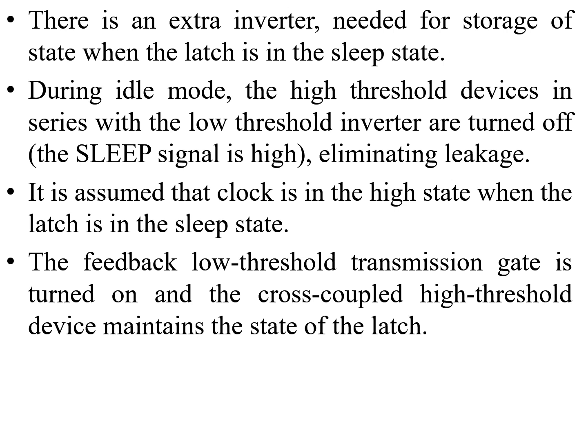It is assumed that the clock is in the high state when the latch is in the sleep state. The feedback low threshold transmission gate is turned on and the cross-coupled high threshold device maintains the state of the latch.